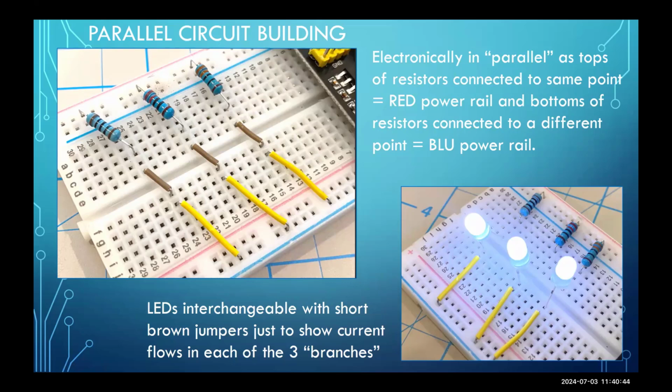In your troubleshooting, one was what? Flip the LED. Second, check your connections if that LED still does not light up. All right. Didn't know you were going to get quizzed, did you? Ha. All right. So now let's go ahead to the next one.